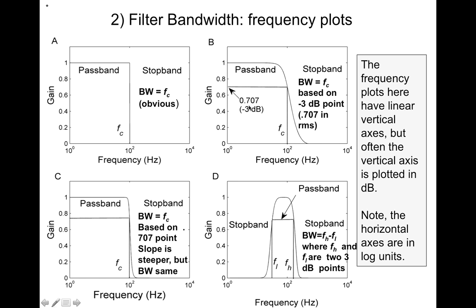So a more realistic kind of filter is not one that has this immediately square shape, but basically one that begins to transition at some frequency below that 100 hertz that you would define as your bandwidth, or what we would call cutoff. In other words, above that level, you don't consider the components to be present in the signal or the filter, and below that level you do.